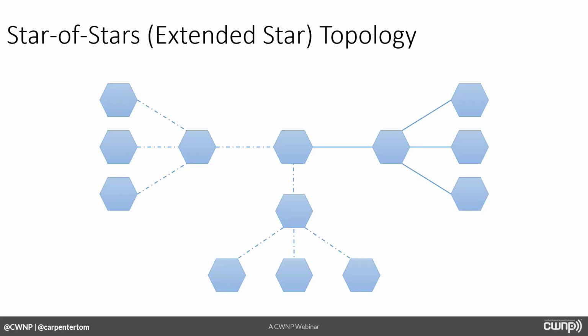All right, so now we need to talk a bit about a topology as we get into LoRaWAN here. There's a topology called star of stars. And basically, a star of stars topology implements a local star that communicates with at least one, but maybe multiple remote stars. LoRaWAN is actually defined in the LoRaWAN specifications as a star of stars topology. So the local LoRa device communicates with the LoRaWAN gateway, and that's the first star. There might be multiple local LoRa devices that are communicating with that LoRaWAN gateway.